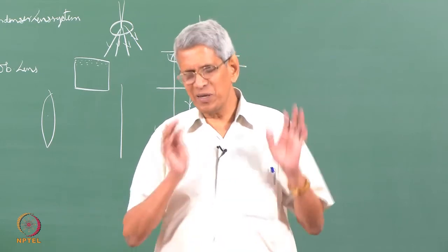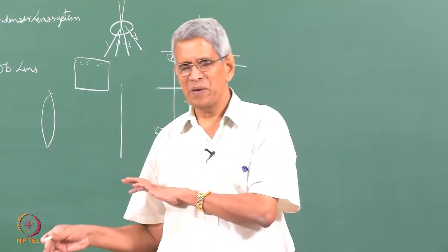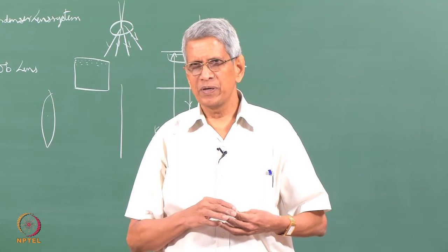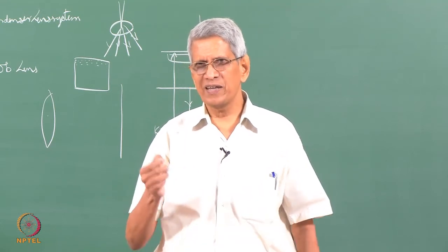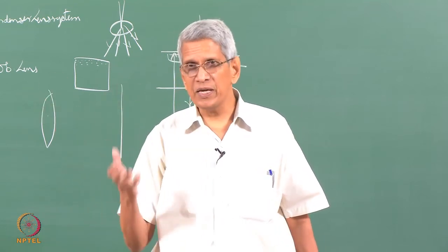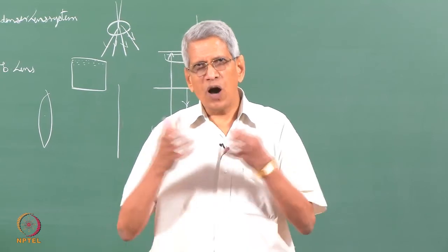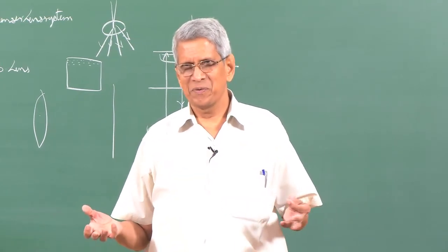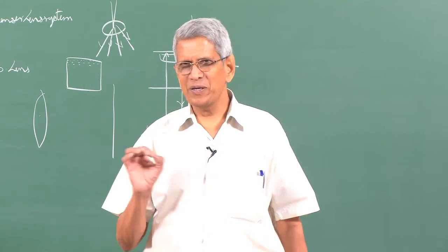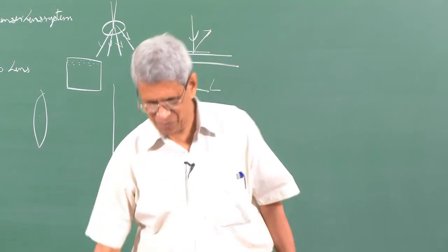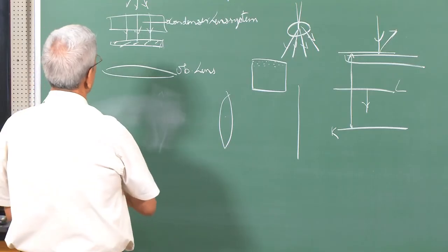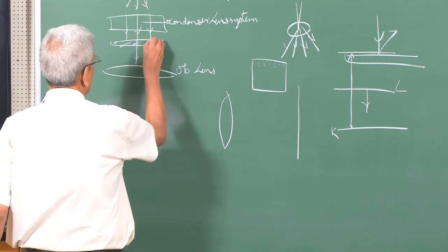That could be done using lenses, where we use a scattered beam, or the way we do in a scanning tunneling microscope or an atomic force microscope. It is essentially atomic force when we bring a probe close to the sample. That is also one way in which we get a microstructure, an atomic resolution microstructure. So, all are microstructures. A general definition of a microstructure is a property distribution in a specimen which has been mapped.